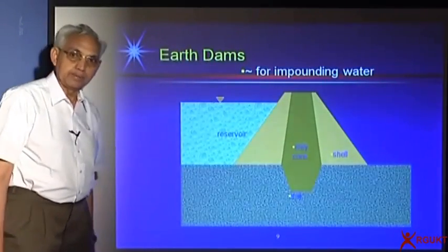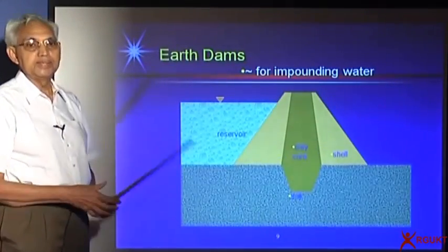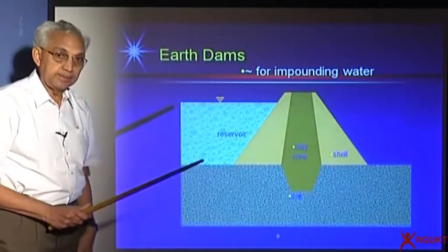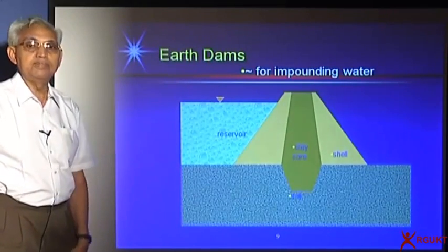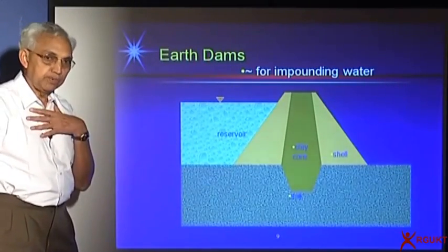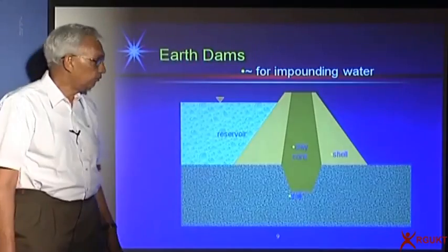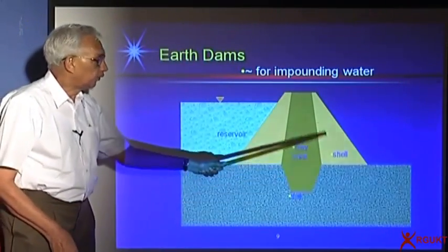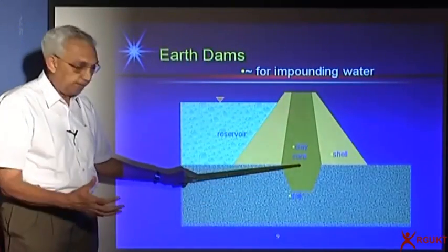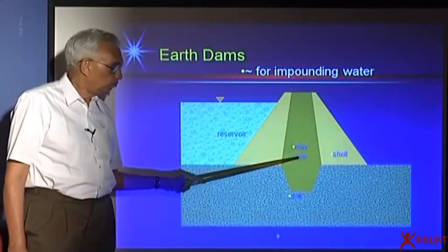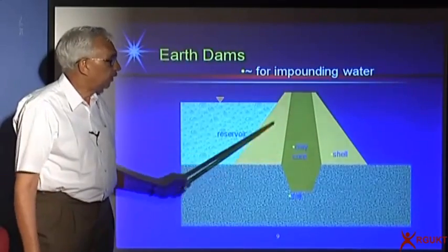You want to store water. How do we do that? In the good old days, for example, Nagarjuna Sagar, they were using a masonry dam. But that being one of the largest, it took a long time. It's very expensive. What they have found is soil itself is a good one. And it's not something new for us. Even our ancestors, the first dam in India was built in the 3rd century in Tamil Nadu. And all they had done was use soil, two different types. So here, for example, I have a fine-grained soil, we call it clay, which will not allow any water to go. And then we provide a coarse-grained soil, we call shell, and then we can build it.